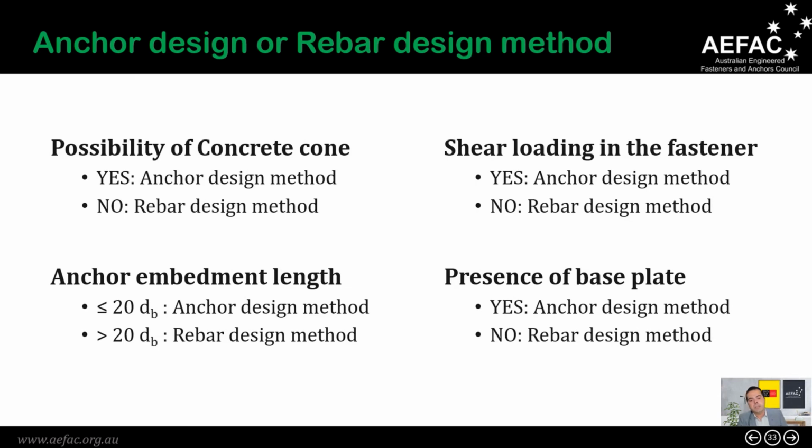Finally, the base plate. Usually we don't need a base plate for the rebar design model because we connect concrete to concrete without using any fixer plate or base plate there. If you need pre-tension force or if you need a fixer plate to connect the element, it is recommended to use anchor design theory.